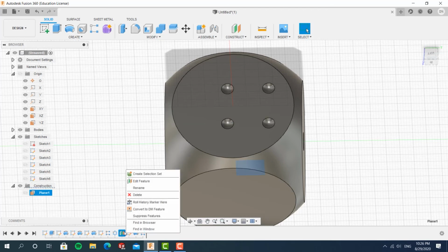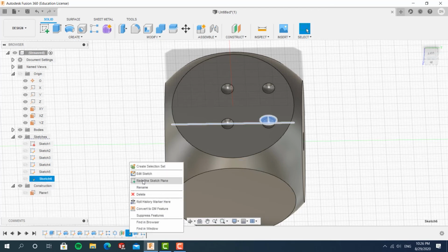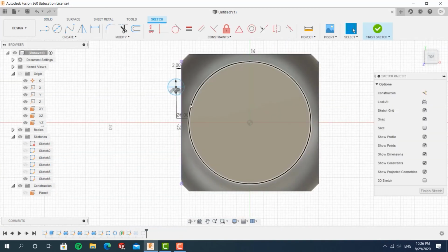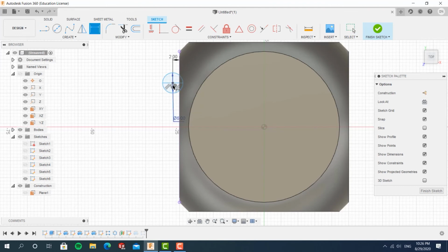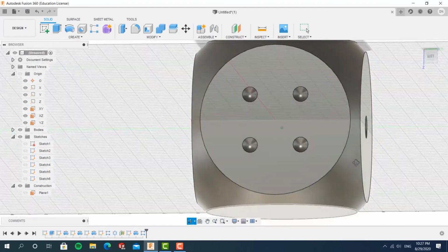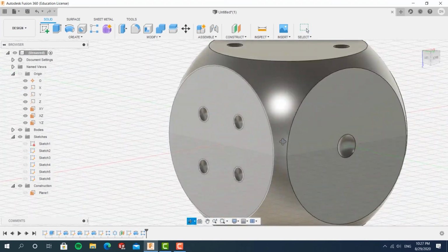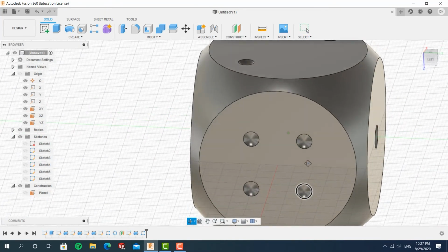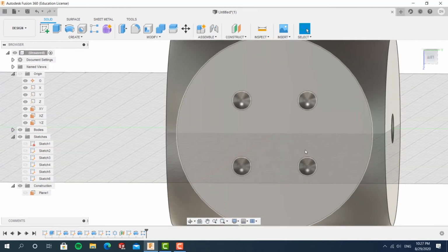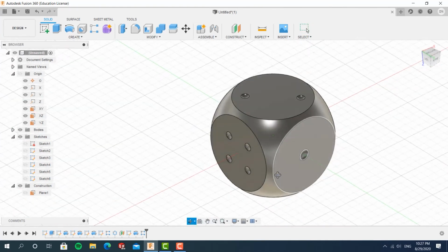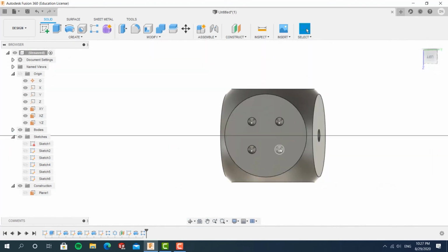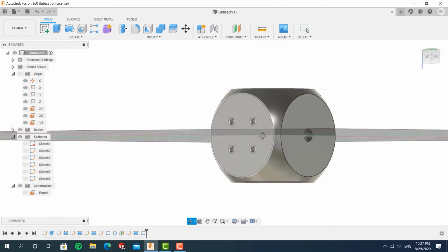So just roll back to the sketch. You can edit it by choosing edit sketch right here. We want it to be 7.5 on the center because it's half of 15. Okay, finish. Yeah, okay. If you feel like this looks a bit too close to each other and too clumped up, another thing you can choose to do is make the distance between the diagonal tiny or something bigger, or just change up the number a bit. But for now, this would work.